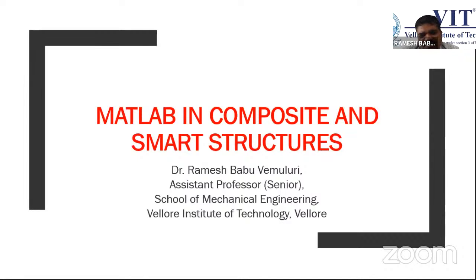Once you take smart structures or smart materials, these are magnetorheological elastomers or various electrorheological fluids. They have a G value. So once you take this G value, the composite structure becomes a smart structure with this layer in between. As we already saw in the morning case, the core layer will have only the G component, also called the shear modulus. So we have to combine this shear modulus in the ABD matrix. Then we follow the same procedure we did for the composite.